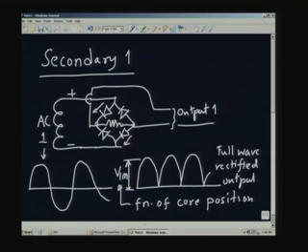So, the signal will pass through like that. Okay. If this becomes negative and this becomes positive, the other 2 diodes are going to do the conduction. So, that is why the output is going to appear for the first half cycle.